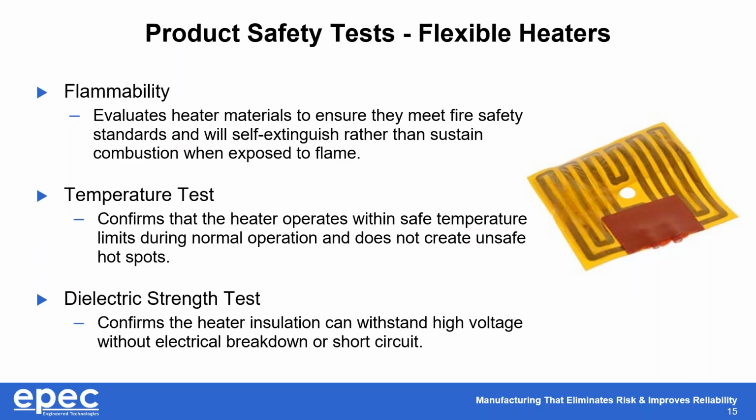Many of these are off-the-shelf materials or compounds that we've been using. So we already have the test data that shows that it already has various favorable flame ratings. The next is a suite of temperature tests where we're energizing the heater and making sure that it achieves its normal operation temperatures and doesn't create a hazard to the user or the equipment. Next is a dielectric strength test. Basically, that there's no risk that under a high voltage situation that the heater will burn out or short circuit.